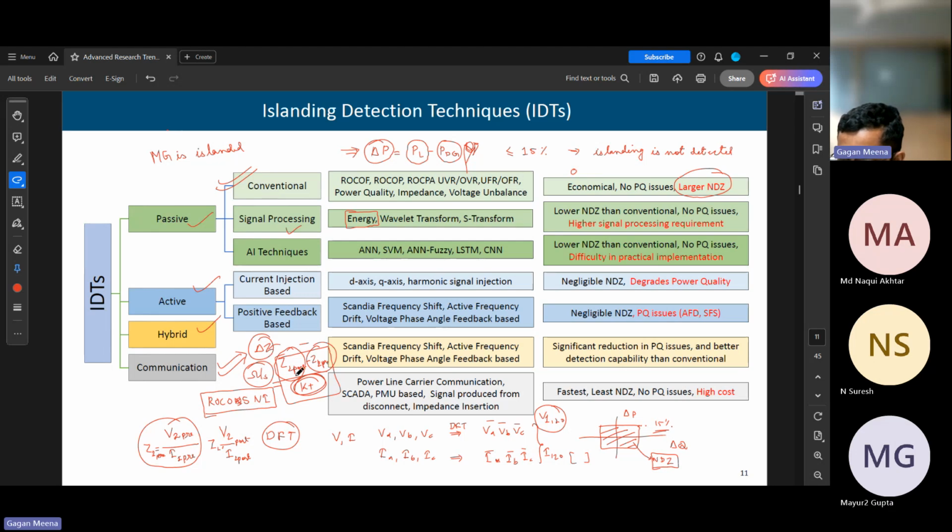But it is not difficult to implement, right? Because we don't have to do anything. Everything is available. We already have all the voltage phasors. We are doing the same thing. The one step we are adding is calculating the sequence component, which can be easily calculated based upon the available phase information. If it is not available, it can be easily added. It is not a big addition.